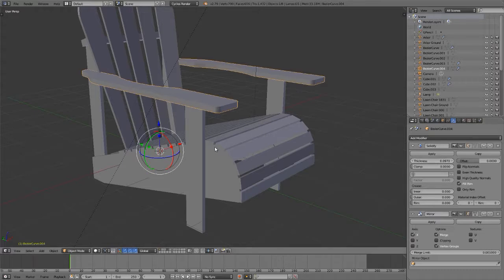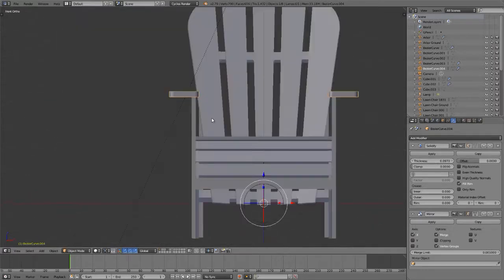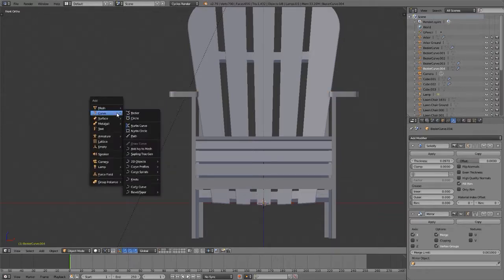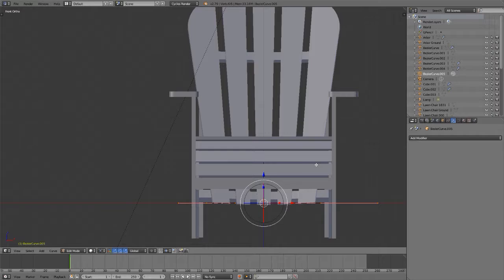So 5 and 1. Let's create a curve in edit mode. G, move it far away. V, change the handle type to vector. And now rotate it 90 degrees. G, put it roughly where it belongs. And continue putting it roughly where it belongs. Take A, I guess I don't know my alphabet, and extrude on the X, F, join those together, take those and move them in. So our rectangle is big and luscious like that and fits into this corner.